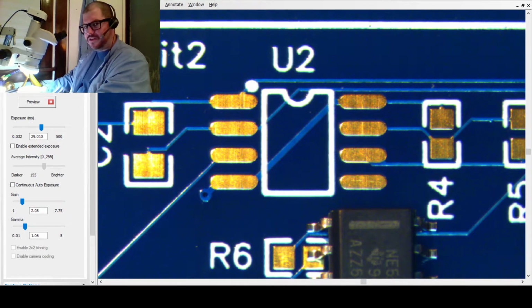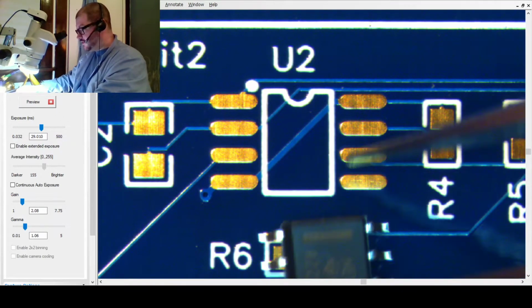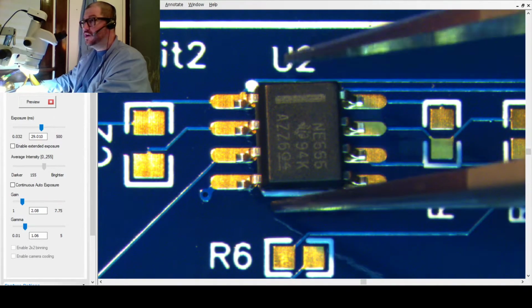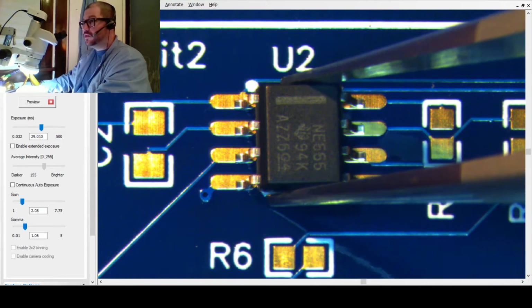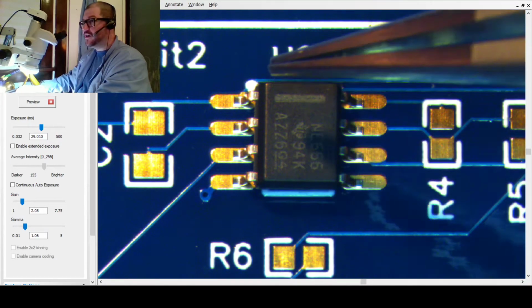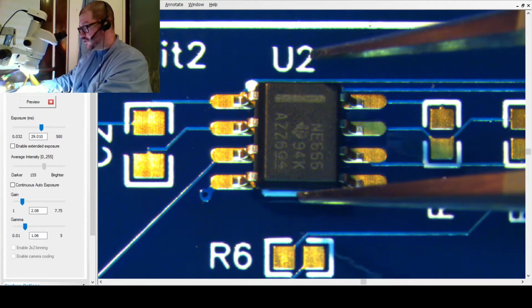Anything with pins on the outside, that's pretty common. That's what I've seen. Not saying I've seen every single microchip out there, but in general, that's what I've seen. If I were to look at the chip, there is a little bar on there, and when I place these two in their correct positions with one another, there is a bar that aligns up with the top part of it there. This is the correct way that the chip should go in. This would be the correct way that it would function normally.